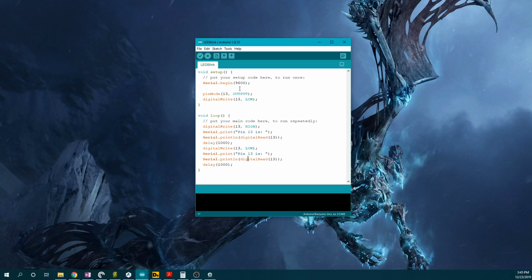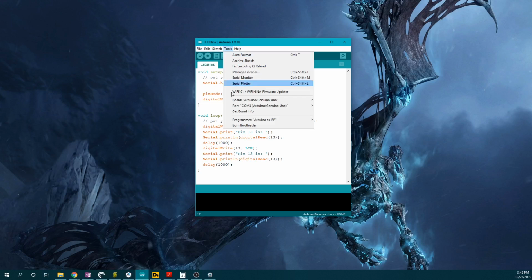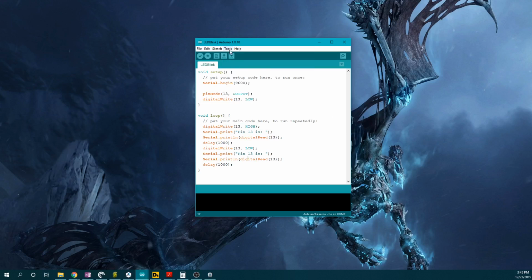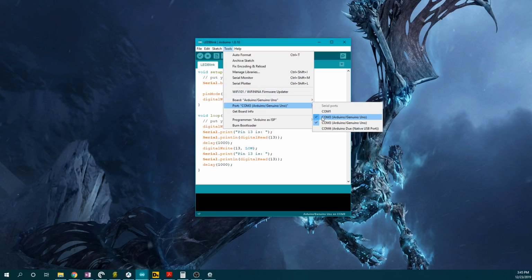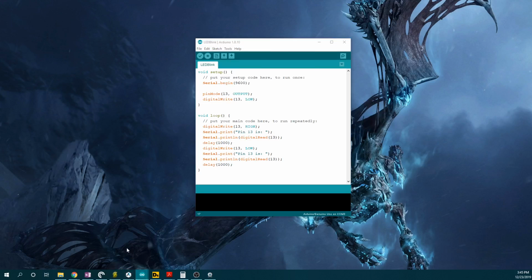So what I've done here is I've taken our blink program and uploaded it to the board. I can upload it again just to show you guys. Make sure that you have the correct COM port assigned, because I have two sketches open.